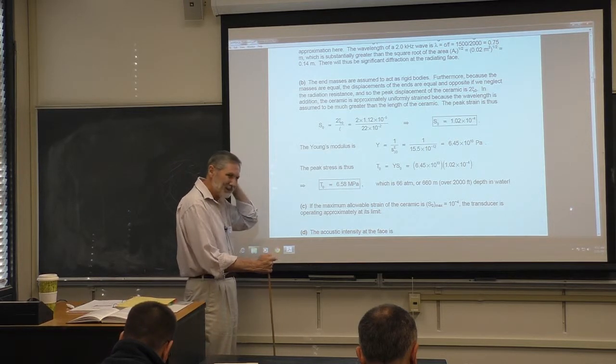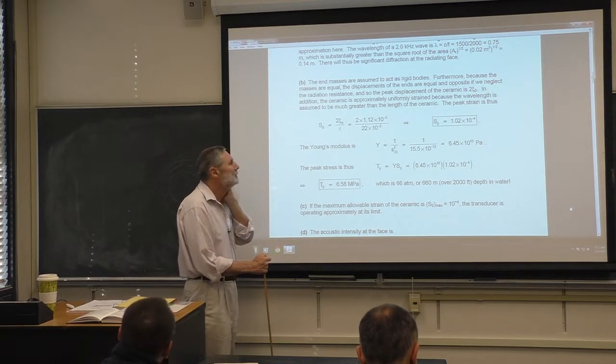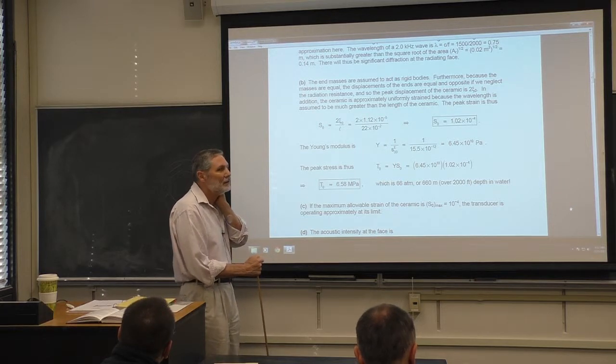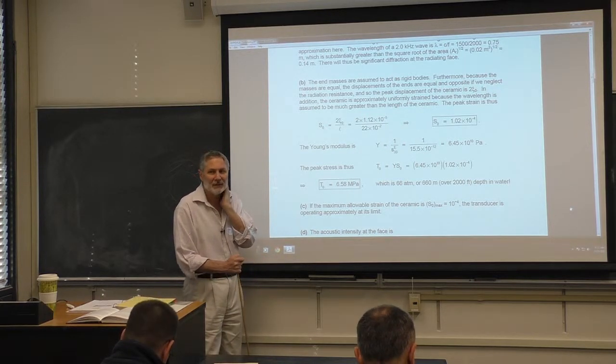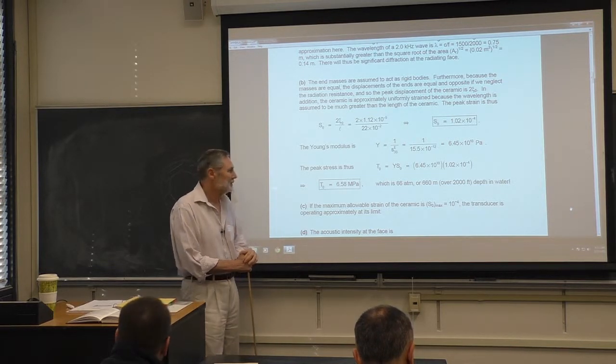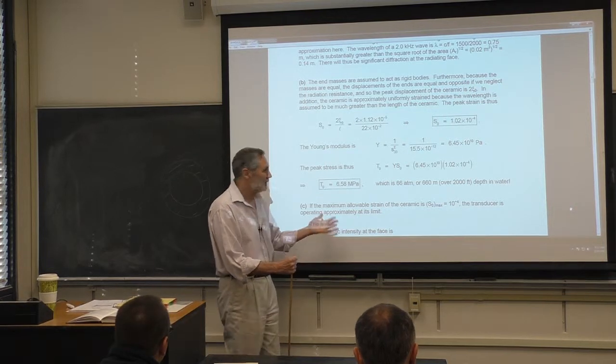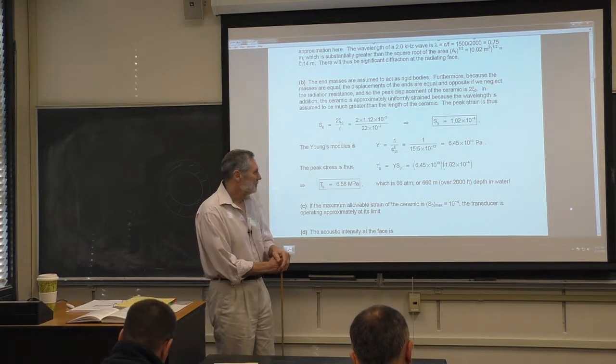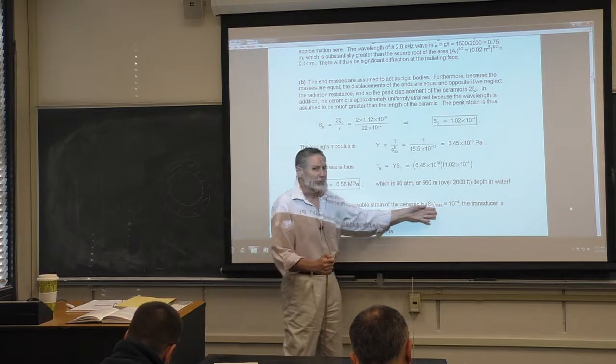I was just thinking here, so we're not including the effect of the clamp bolt here, right? So that would change things. In fact, that's one of the reasons you have the clamp. That's really a big part of the reason why you have a clamp bolt.